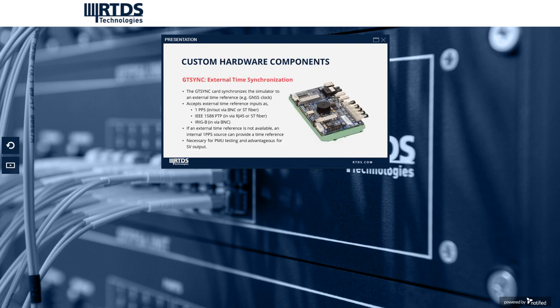Finally, in the presentation and demo, you will see Shane talking about synchronization. And I just wanted to mention the hardware that makes that possible. It's called the GT Sync card. So this card synchronizes the RTDS simulator's time step to an external time reference, like a GPS clock. And it can accept several different external time reference inputs. In the demo, we are using IEEE 1588 PTP, but we're also capable of 1 PPS and IRIG-B.